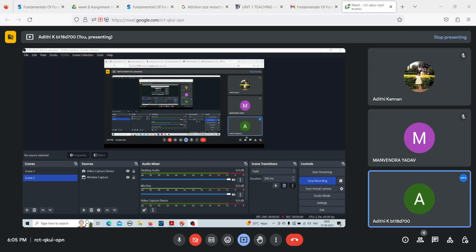So Rittinger's law is based on the fact that energy consumption is directly proportional to the surface area and not the linear dimension. So statement 1 is false, and this law is used in cases of fine grinding. That is, when you want to finely grind your particle and xp is much less than xf, you use Rittinger's law, which is much more accurate. So statement 2 is true. So the answer here is option E.